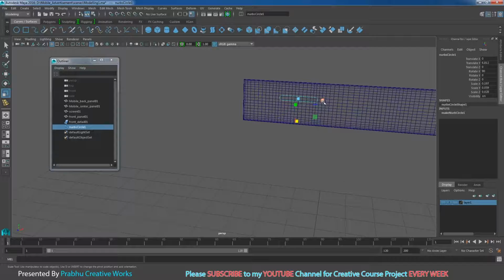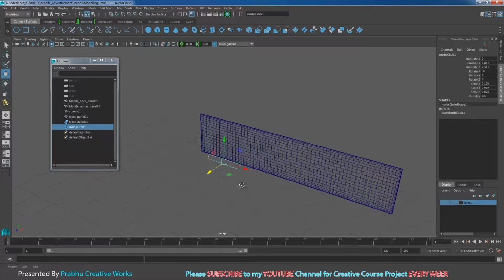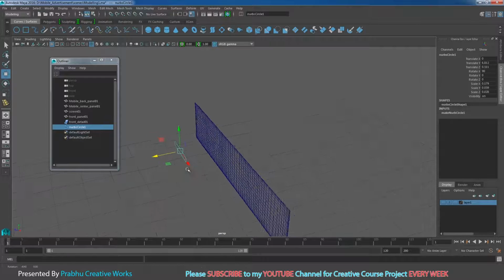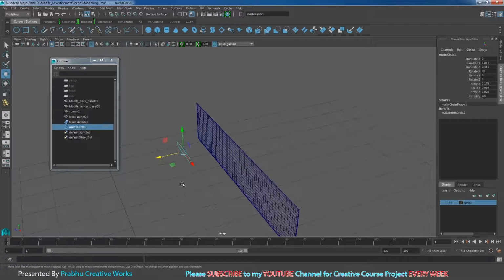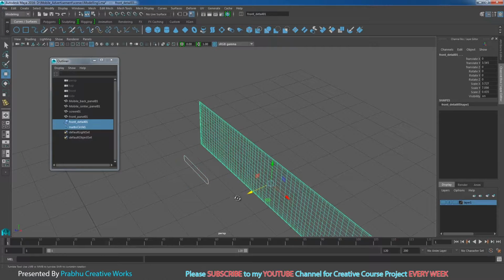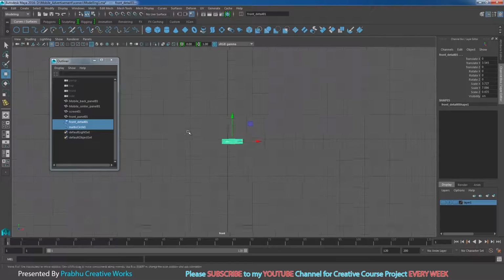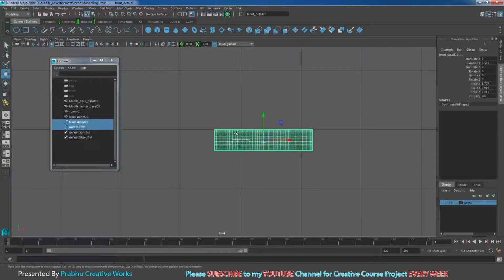So I want to reduce the scale a little bit, like this. Okay, press W, move in Z. So you want to keep this node circle in front side. So I will select my node circle and shift select my front detail mesh. Go to front view.